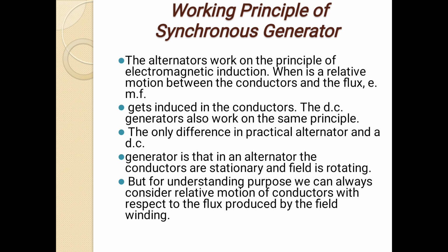Working principle of the synchronous generator. The alternator works on the principle of electromagnetic induction: when there is relative motion between conductor and flux, an EMF is induced in the conductor. The DC generator also works on the same principle. The only practical difference between an alternator and a DC generator is that in the alternator the conductors are stationary and the field is rotating.